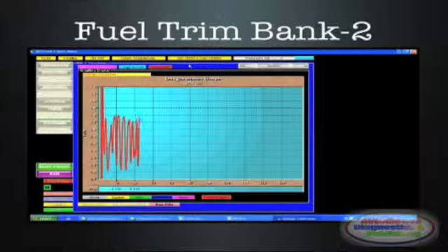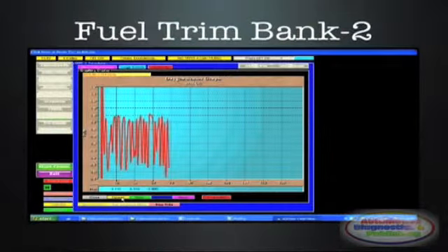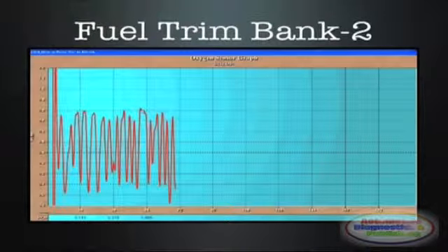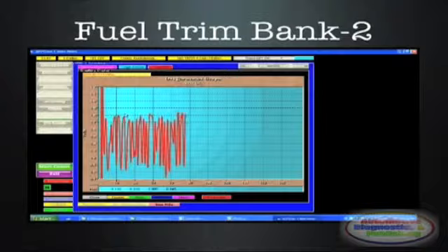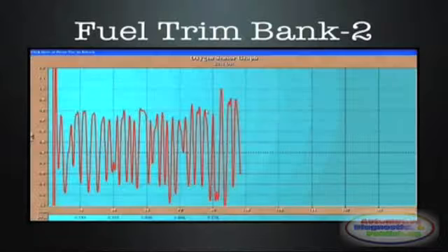Use the short-term to check for vacuum leaks, together with any other technique, such as propane enrichment using the right tool. A minimum of 150 millivolts or 0.150 volts and a maximum of 800 millivolts or so, about 0.800 volts is desirable.